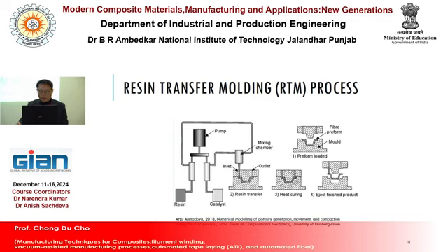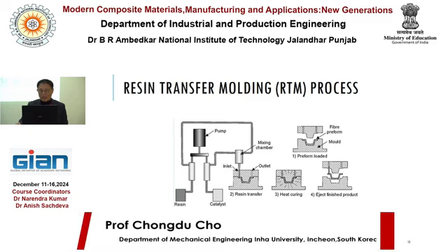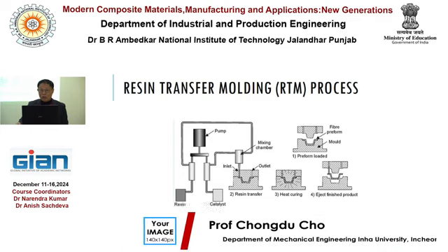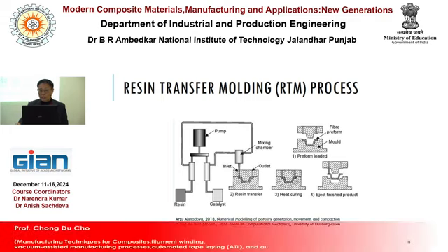So after the cavity is filled by molten resin, heat curing is needed. So of course, before the resin injection, you need to get a fiber preform inside. Okay, so before injecting resin, the fiber preform must be placed into the cavity.